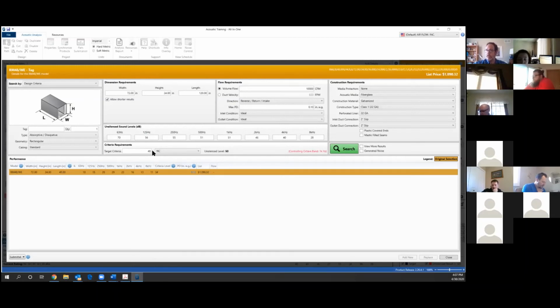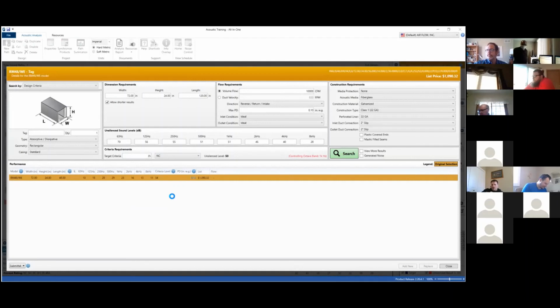But we did just another, oh, I selected this at 40. Let's change that to 35. Oh, well, we were already there. See that? It selected us to 35 even though I changed that. So if I research, it'll give me the same silencer. Again, it's telling us where our issue is. So we're not worried about whether we're off by 1 or 2 in the 63 or 8,000 hertz octave bands. We're only worried about our controlling bands.